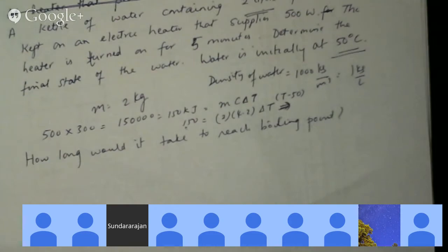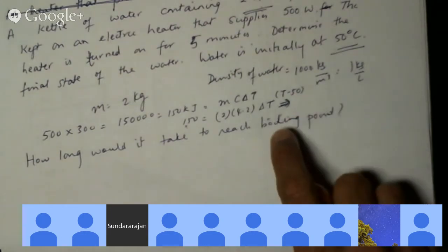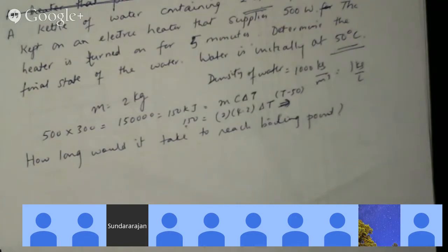Okay, so it still remains water, right? Yes. So how long does it take to reach boiling point? A while. So you figure that out. From 68, so it's now at 68. How long do we need to leave the heater on? You basically use Q equals MC delta T, except this time your delta T would be 50, and you get 420 kilojoules.